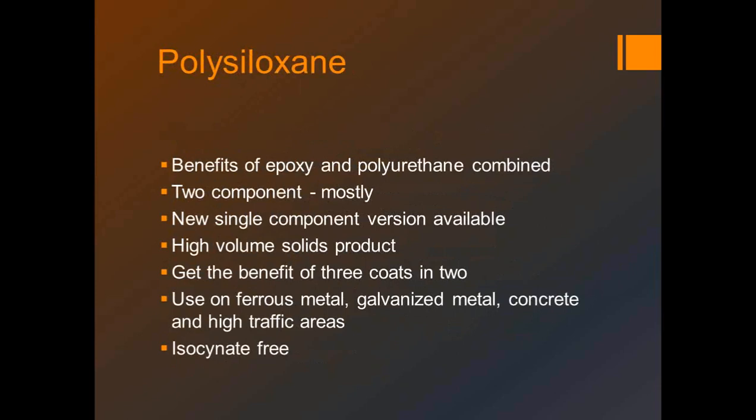So I would stay with 100% acrylic if I was looking at it for a Hardie plank or a cementitious board type siding. One of the places where it is good, though, are the large exposed steel things that are going to be exposed for a long time, and you want good service life.